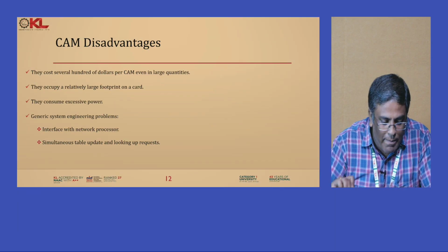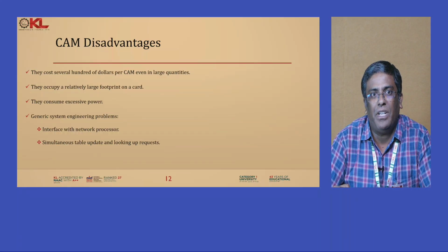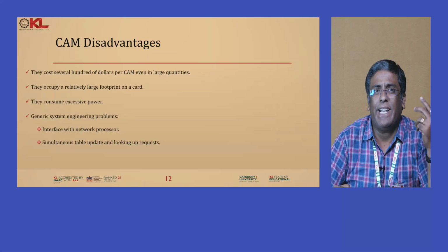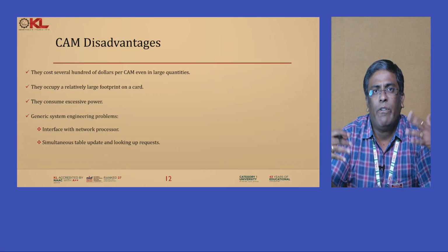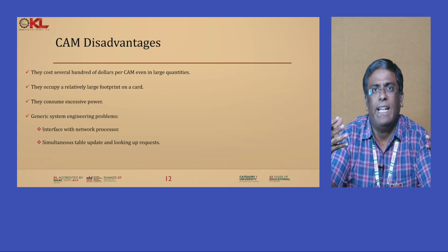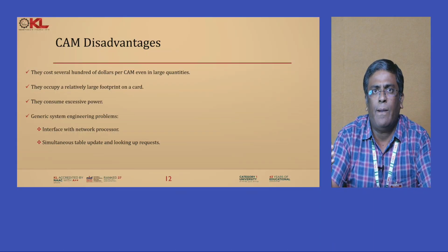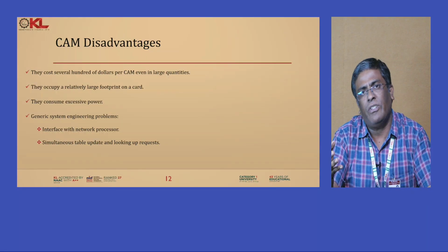And when I say the drawback, the cost of the CAM for fabrication, the unit of the CAM, is going to be costlier because it requires more than SRAM cells, more than the conventional memory cells. It requires some extra elements like encoder, data and registers to support this content addressable searching. So it occupies a larger area and has more transistors, which increases the cost of the CAM devices.